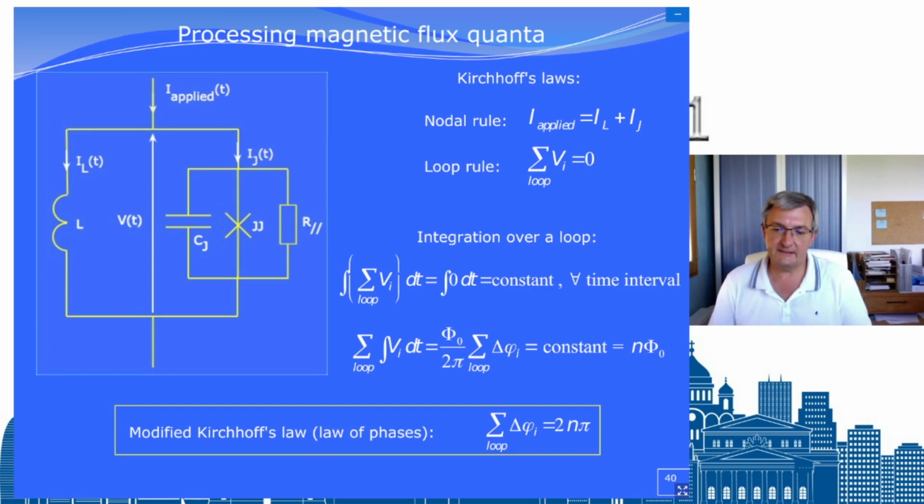So how do we do that? The problem is to have one pulse only, and not a train. We do that in a very simple way. We take a Josephson junction, which is the electrical model, and I just short circuit it with an inductance. In some way, I make a loop, right? It looks like a SQUID. In fact, it is a SQUID, except that in this loop, instead of having two junctions, I have just one. But it's also a SQUID. It's a quantum interference device.